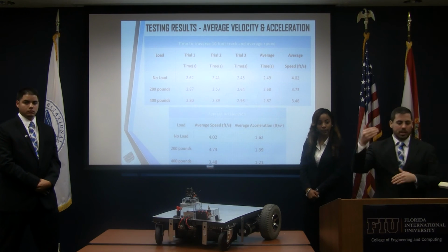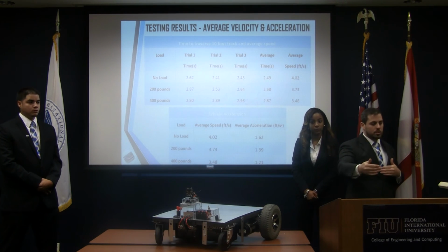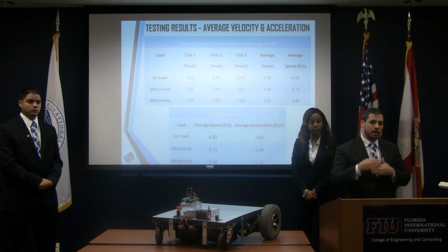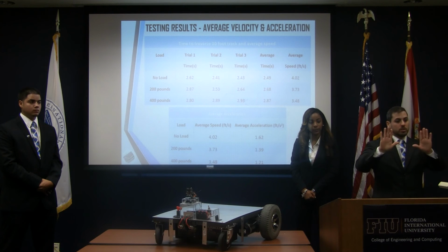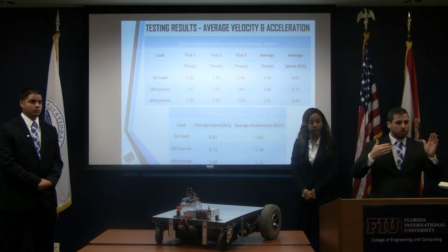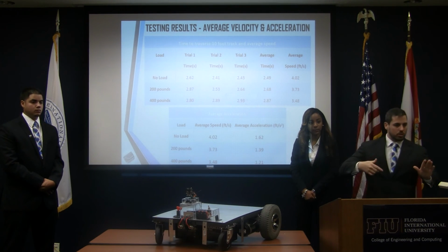And so if it gets to a threshold, it knows that it's, let's say, 2 feet away. If you program it that way, it'll be 2 feet away from you, and it can follow you at 2 feet. But if the image itself gets too big, it knows that it's too close, and it'll back up. And if it gets too small, it'll continue to go forward, basically.